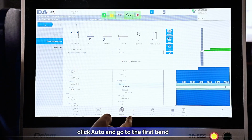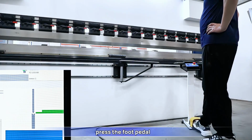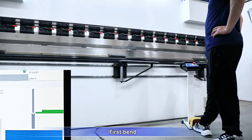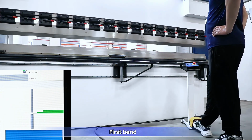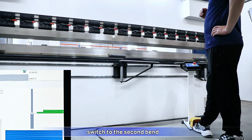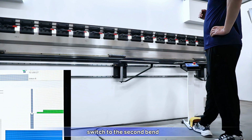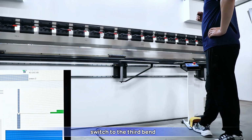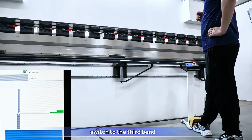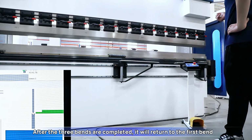Click Auto and go to the first bend. Press Run. Press the foot pedal. First bend. Switch to the second bend. Switch to the third bend. After the 3 bends are completed, it will return to the first bend.